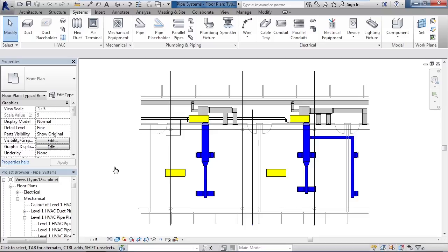In this lesson, we'll cover piped systems. Before you start to actually build your layout of different pipes and components of your pipes, whether that be fittings or accessories, you need to define a pipe system. The pipe system is technically the glue that holds everything together. It's also needed for analysis. Basically, it'll analyze everything in that system or what belongs to that system.